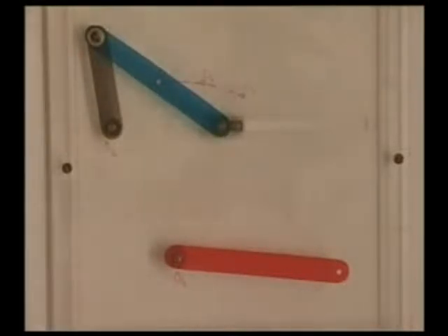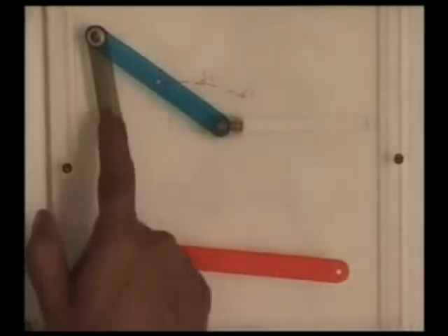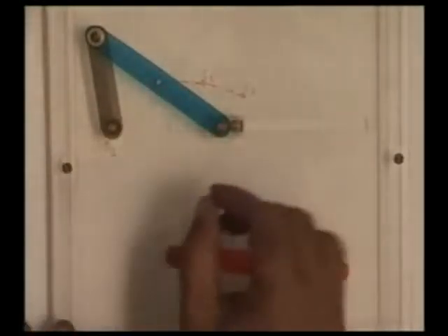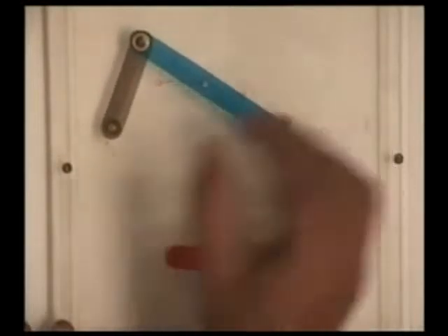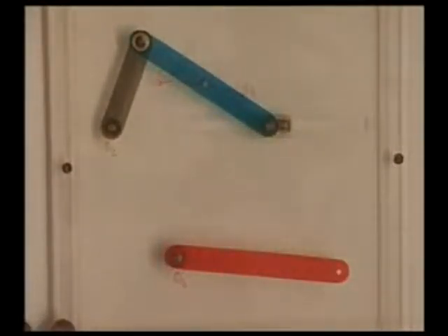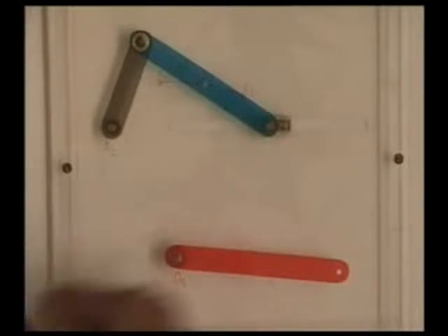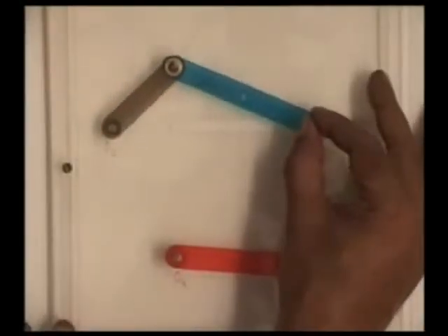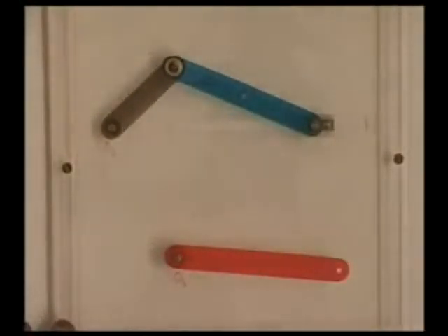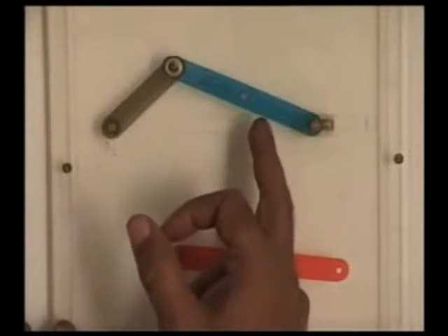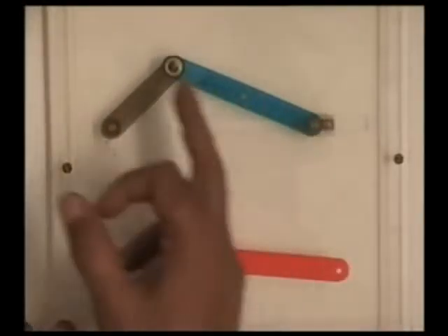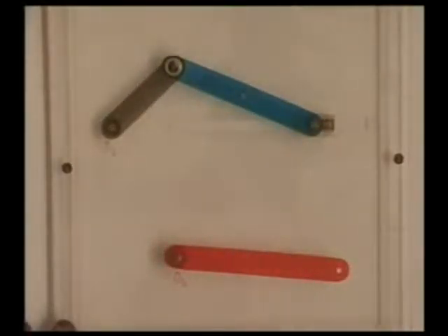To solve this problem, first we design a slider crank mechanism. This is the slider crank mechanism such that this pair of coordinated movement from first to second configuration and second to third configuration can be designed. This we have done just now. If we specify theta 212, theta 223 and the corresponding S12, S23, I can always design this slider crank mechanism.